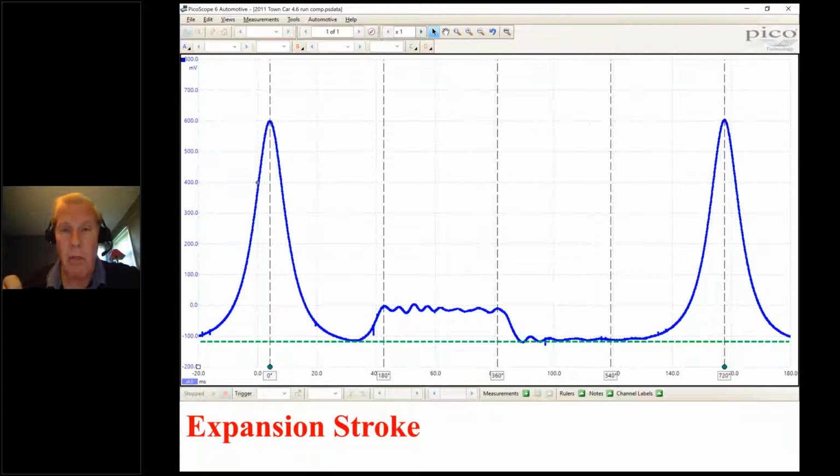When you have significant problems with cam timing, there will be a difference. For example, if I have a double overhead cam engine and the exhaust cam is retarded, which means everything occurs late, the exhaust valve will open later. So instead of opening here as an example, it would open over here, and there would be more vacuum pulled until that valve opened. So not only does the exhaust valve open late, it closes later, which means it closes into overlap, which gives the intake low vacuum.